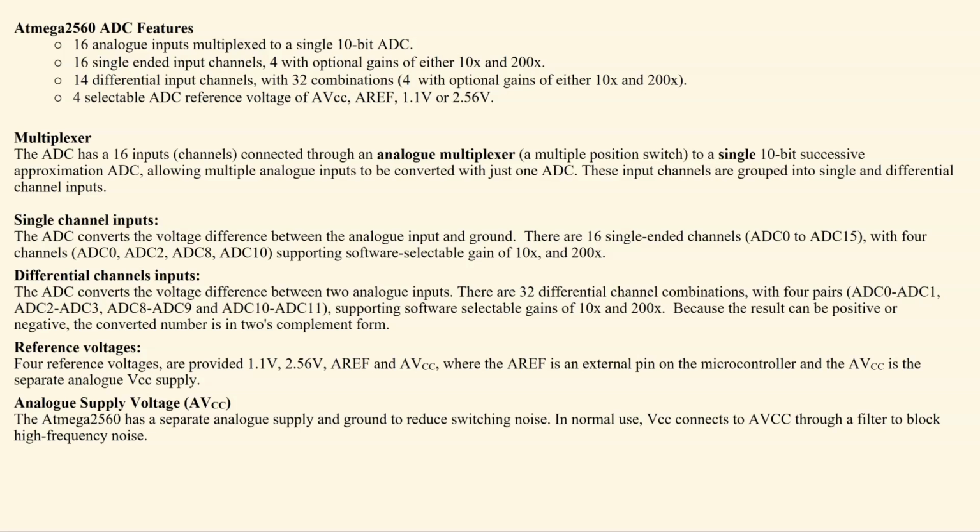The ADC also has 4 reference voltages. We have internally 1.1 and 2.56 volts. We have a reference on the external pin, and we can look at the AVCC.